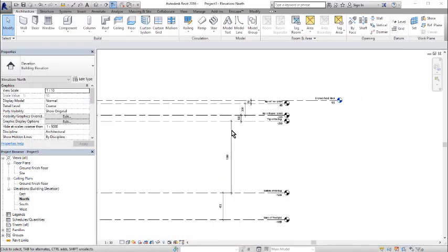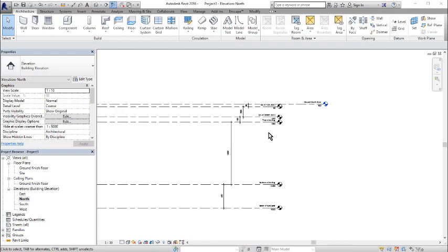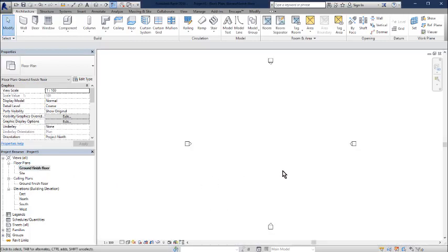All right, so now what we need to do is to start modeling our footing, right? And the designs may vary, but we're going to use a default footing. Now I'm going to switch to our ground finish floor level, right? Notice that you're not seeing the other levels here because those are empty levels which are used only for referencing.